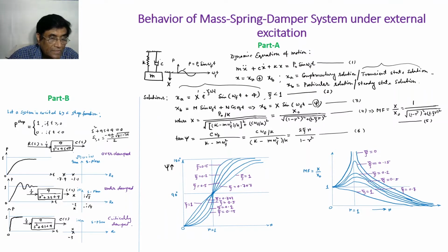So the situation is overdamped, and the roots will be negative definite, and they will be on the negative real axis. They are real and always negative, so they will lie on this axis. This is the S-plane or Argand diagram, as you can call it, many names. Here we can plot the real axis and imaginary axis orthogonal to each other.